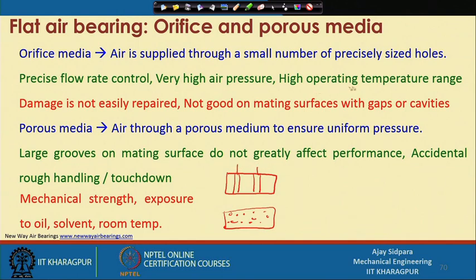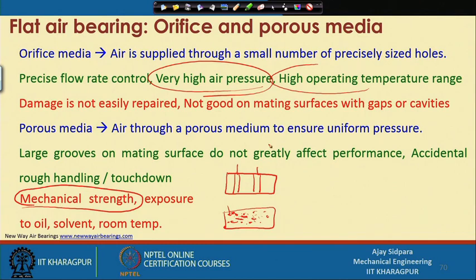Here you can go with a high pressure, we know that high pressure is not a problem, but if you provide a high pressure here, what is going to happen is that this material is very weak in strength, because this inherent porosity will make this material a little bit weak. When you are providing high pressure velocity of this particular oil, whatever porous things are there will try to merge with each other and that will start deforming the structure. So, mechanical strength is a big issue, you cannot actually go beyond a certain pressure limit, and that depends on what material you are using.